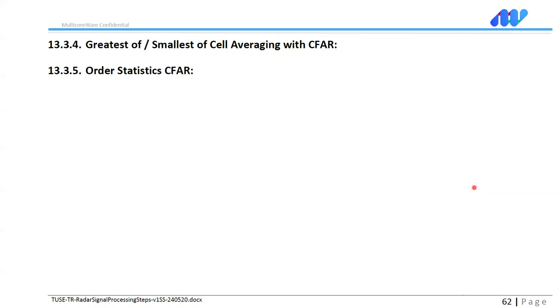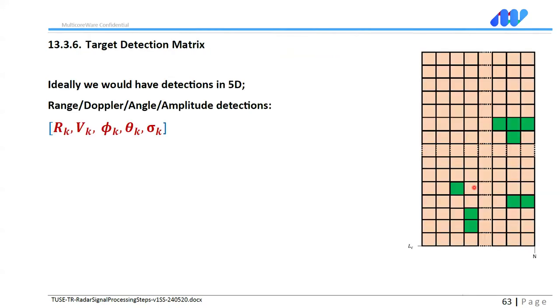And this whole process is called the RSP pipeline. Normally it's the pre-processing, and some people will be working on post-processing, which includes perception for fall detection, object detection, etc. So what the pre-processing hands them is a list of target detections, and we call it the target detection matrix. For each line, you have a target with a defined range, velocity, angle, amplitude, whatever you want to have. So this list of data is our output.